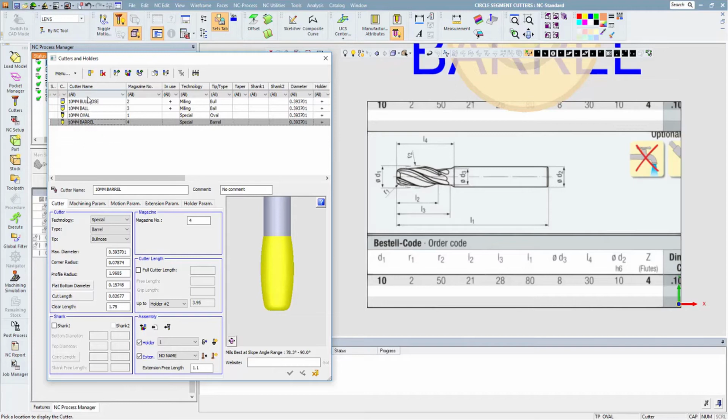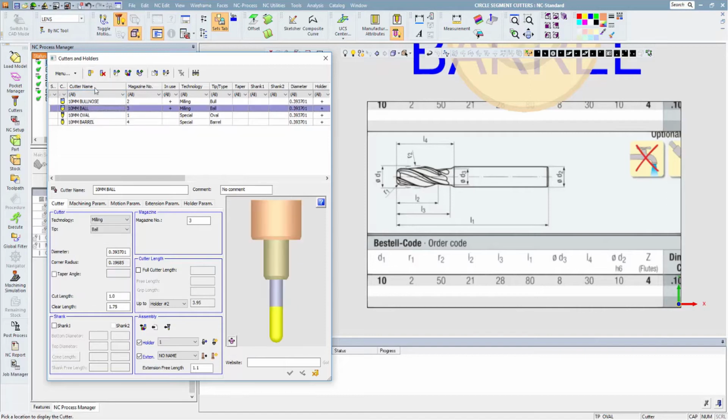And now we have one more tool to set up. The barrel is really the trickiest one, because if this information isn't here, you don't have the end radius or you don't have the flat, you have to get that information. We need one of the two. So in this case, the cutter manufacturer provides that information. It's just not right in here in this quick display. So we just snag that file from the website and do a quick check. So now we'll move on to